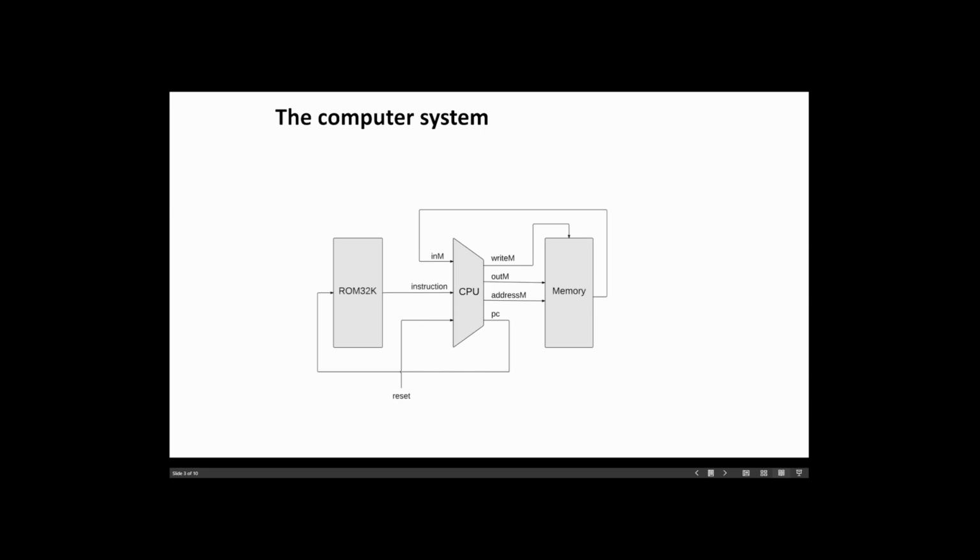This diagram was used to implement the Hack computer in one of the tasks that we have done previously. Here it can be seen that the CPU takes its instruction input from the instruction memory and also takes the value of the selected data memory register as one of its inputs. The reset input is a value that tells whether we bring the CPU back to its initial state or, to be specific, to start the operation of the CPU all over again.